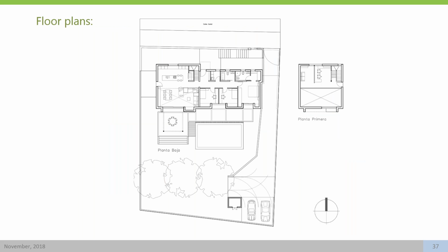And almost all the main spaces in this project are on the ground floor. But the studio forms a mezzanine that communicates with the dining living room by a double high space. You can see it here. Also, as suggested by the optimization analysis, to meet the performance objectives, the overall window to wall ratio in the main spaces was kept at 0.25. This is enough to provide good views for the occupants, and the daylighting analysis that I will explain later showed us that daylighting levels are good.